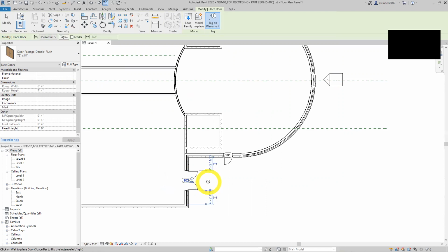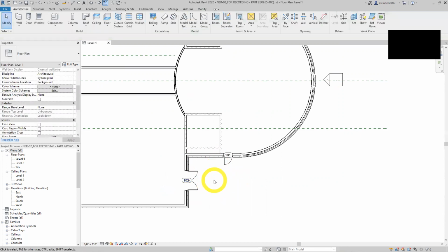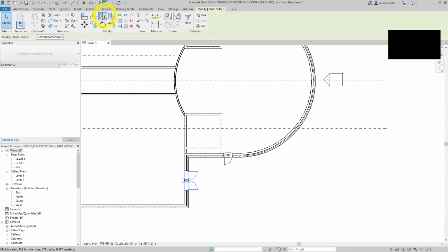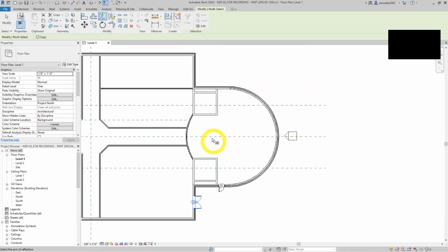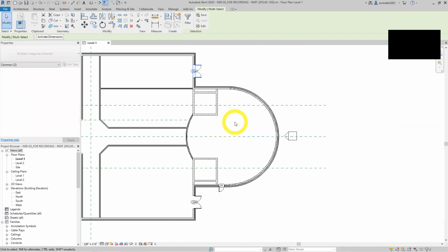That works. You notice how my dimensions were even as I placed it. Oftentimes Revit likes to stay symmetrical. That's helpful to start a lot of times. We just need to get in the middle of a wall or something like that, just like we did there. I added a tag right away. It didn't do it in the book, which is whatever. We're going to mirror both these along the reference plane in the middle. So I have one on the top, one on the bottom. Select the wall, mirror, pick axis. There we go. Escape.